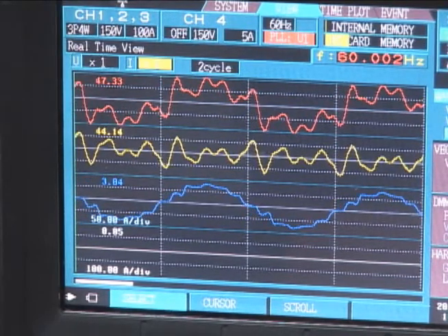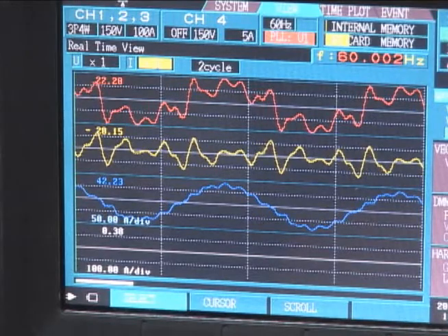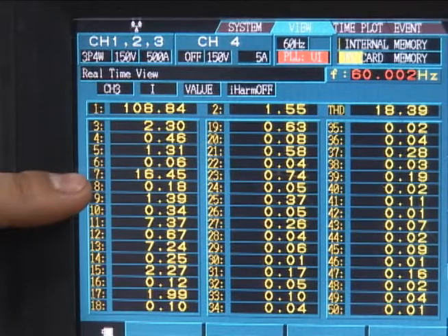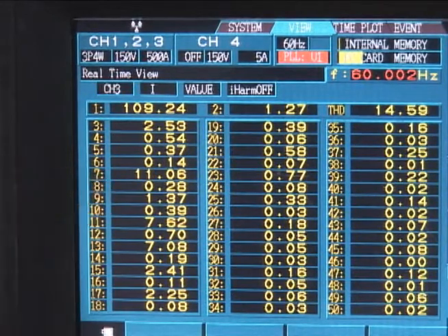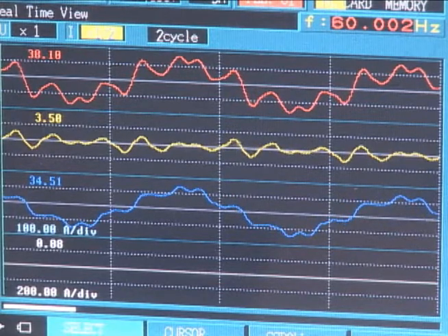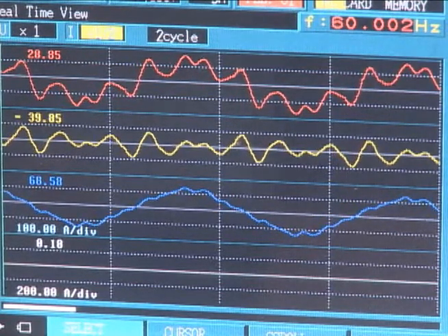The filter is then programmed to filter the 7th harmonic completely. The corresponding bar in the spectrum disappears, and the line current is even closer to a perfect sine wave at the fundamental frequency. We shall now select all the harmonics and perform maximum filtering. All the harmonics disappear, and the line current is a clean sine wave.